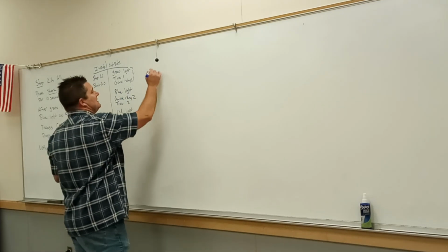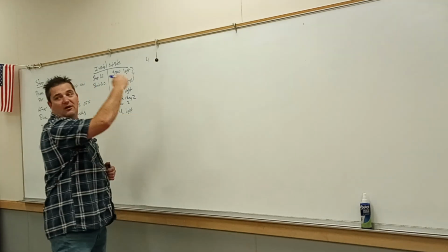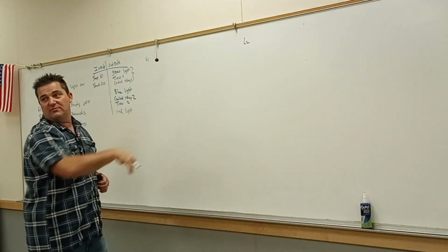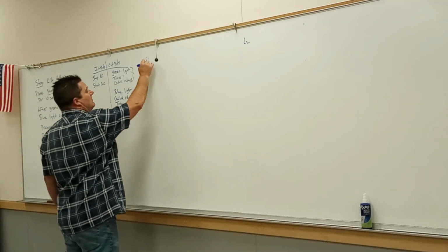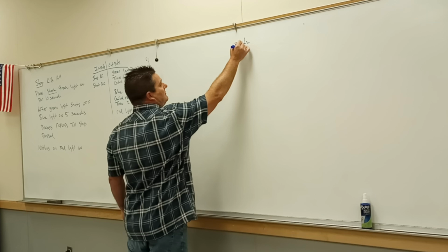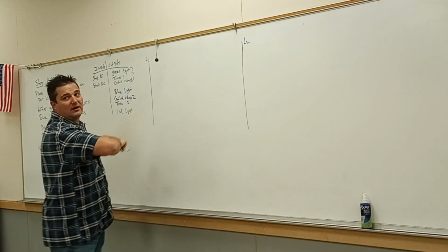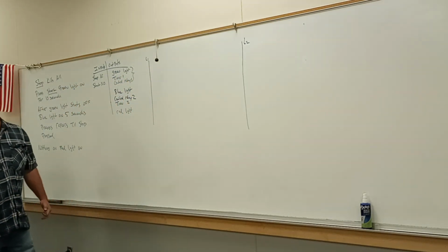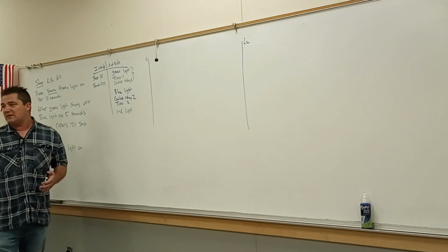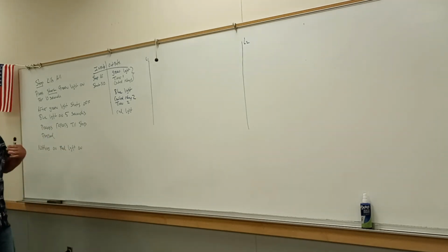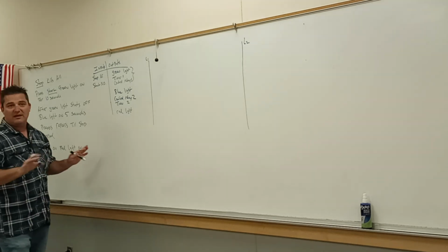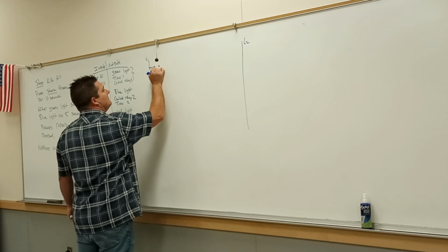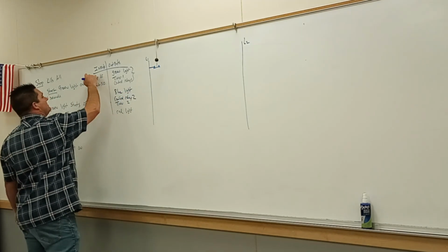So we take these inputs and outputs. We know that L1 is always on the left. L2 is always going to be on the right. Our rails go straight down and our runs go across. So since stop kills all, the way I look at it, like every fairy tale, once upon a time, stop kills all, to me, is the beginning of the story. That way it makes it very, very user friendly. So we have our stop button. Normally closed, check, got him.